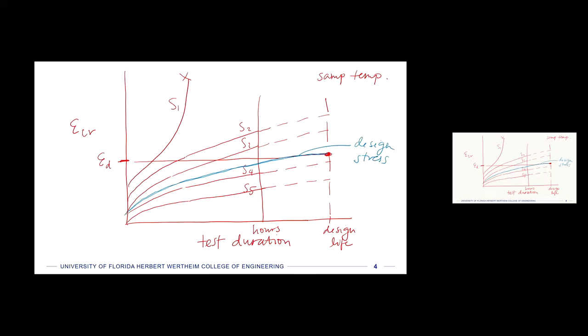The next one is called the mechanical acceleration method. So I'm just going to call it number 2, mechanical acceleration, and that is what it sounds like. We have a much increased level of stress applied in the experiment. And so if we have stress levels as an input to the experiment, then this is actually not a pure creep test. We put a stress level in, but what we really do is control the strain. So this is actually a stress relaxation experiment.